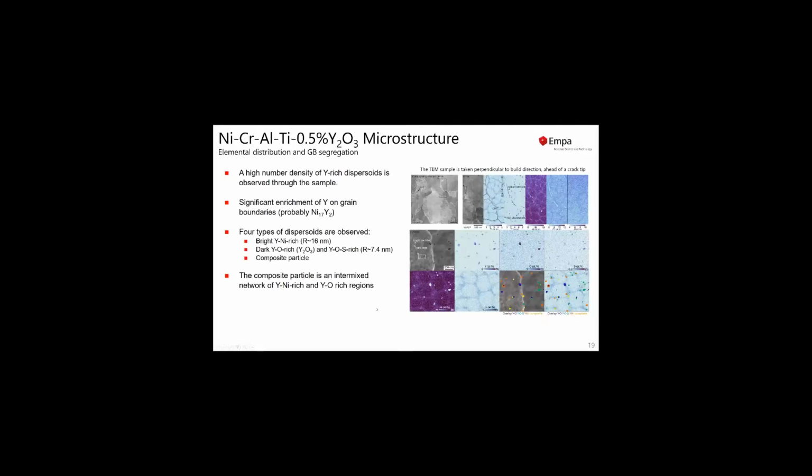So this was about the processing. Let's have a first conclusion. What we can basically say is, we can fabricate ODS nickel-based superalloys, but we do see different things. The addition of yttrium oxide nanodispersoids to that gamma prime strengthened nickel superalloy leads to pronounced slag formation. Despite the short melt pool lifetimes, it seems that the overheating of the molten nickel alloy allows for the reaction of yttrium oxide with aluminium. And this forms a ternary compound with a reduced melting point.